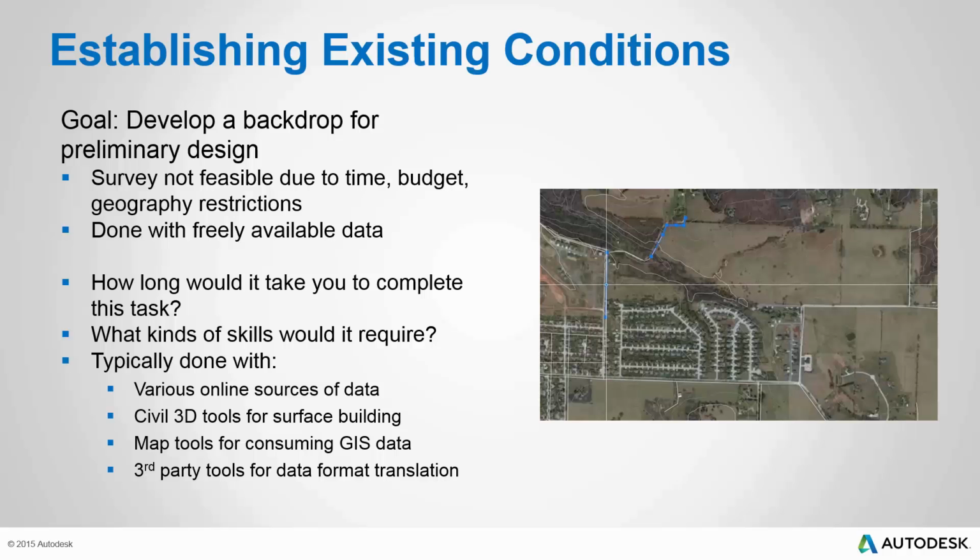And it doesn't have to just be survey. It could be having the site flown or having LiDAR data collected. Whatever means is being used to get accurate existing ground information, it's just not time to do that yet. And you need to develop this backdrop with freely available data. With all this in mind, how long would it take you or your staff to complete this task? And what kinds of skills would it require?